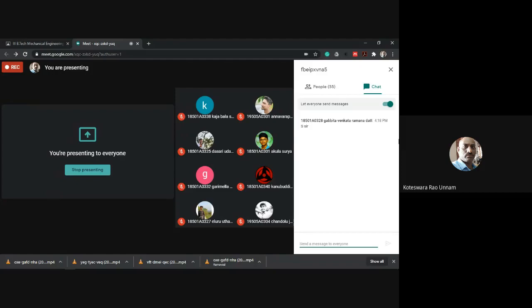Then e is the eccentricity, x bar and y bar. X bar means x coordinate of the center of gravity of the riveted joint. Y bar, similarly. Theta is the angle between primary and secondary loads in degrees. So those are the parameters we are going to come across in the design of these riveted joints.